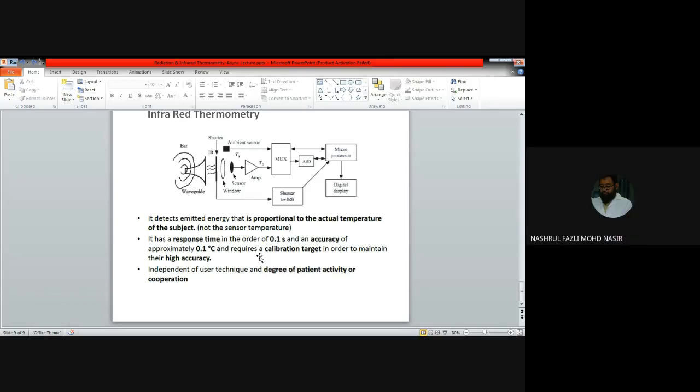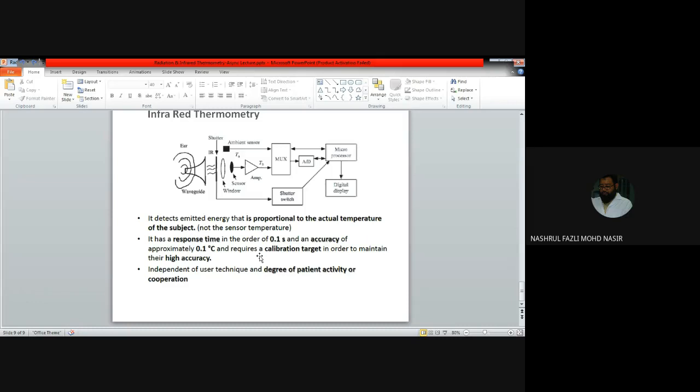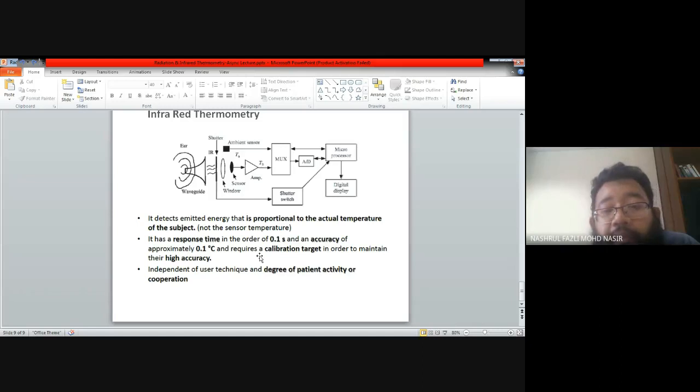It depends on how you are going to use it and for what, and it will be influenced by the cost. If you want it to be more accurate, more precise, maybe you can use a thermistor. If you are looking at something much cheaper, you can choose a thermocouple.